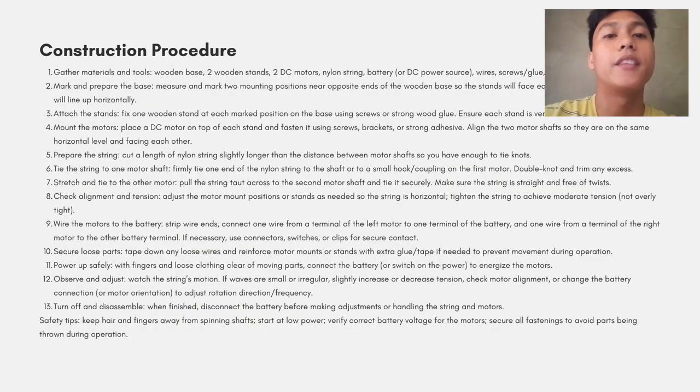When finished, disconnect the battery before making adjustments or handling the string and motors. Safety tips: keep hair and fingers away from the spinning shaft. Start at low power, verify correct battery voltage for the motors, and secure all fastenings to avoid parts being thrown during operation.